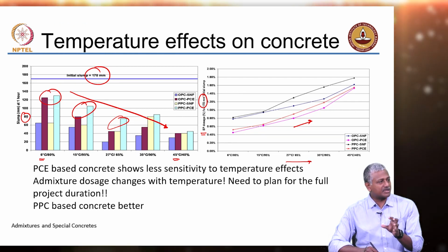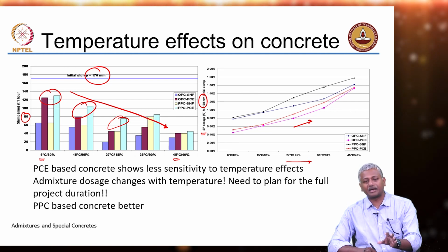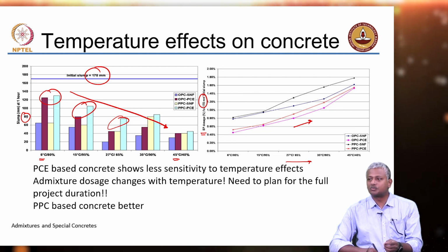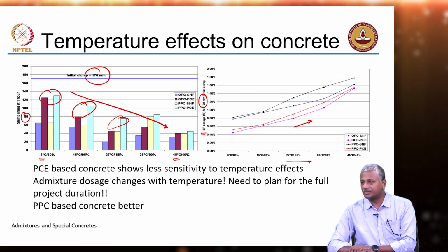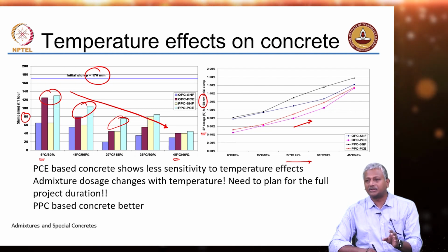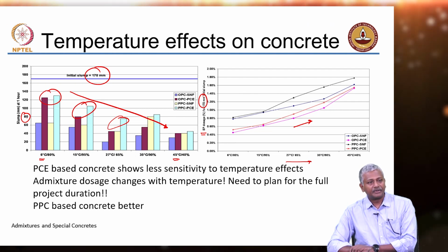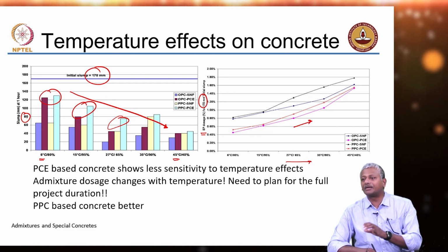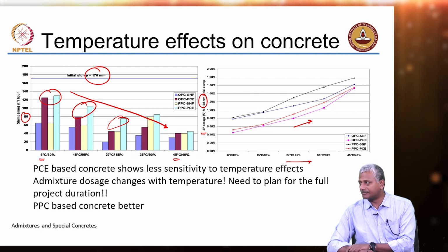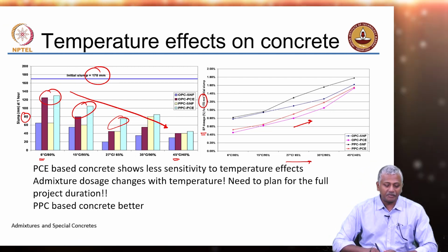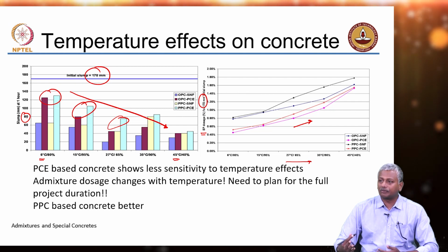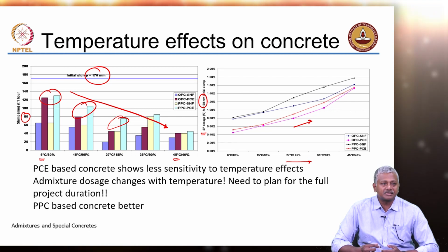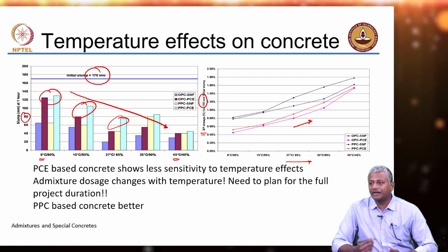Around 80 to 100 mm slump is where you get saturation dosage. I mean, this is not a scientific assessment, this is more of a data based assessment, that when you are close to the saturation dosage of the admixture, you have about 80 to 100 mm slump. So, that means the higher the slump that you design initially for your mix, the greater will be the overdose of the admixture, right. So, if the same test had been done at an initial slump value of 220 millimeters, probably the slump retention could have been better than 100 at 1 hour.